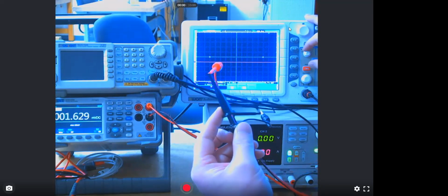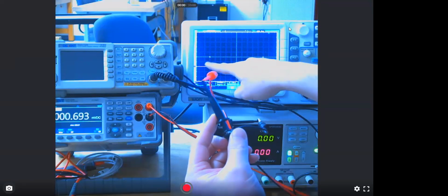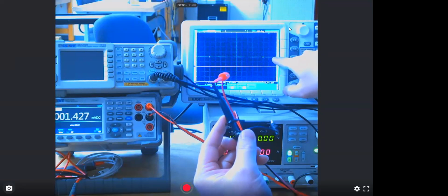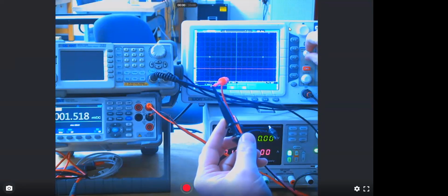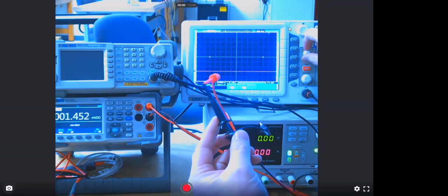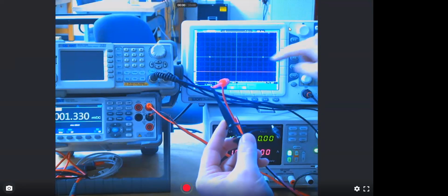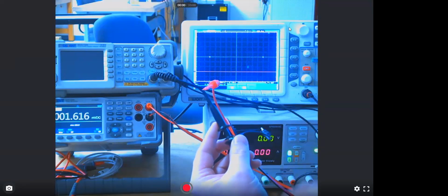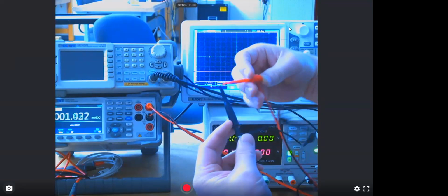What if I move the vertical position of channel 1 down? I think one thing that was sort of confusing you all is you tend to think visually, I at least tend to think that this emboldened middle line is 0. You're zeroing that line wherever you want to. The only point of moving this up and down is so that when you apply a voltage to it, you can see it on the screen. But if I move it down here, it's still going to go up 1 division because I'm putting 1 volt on it. See that?